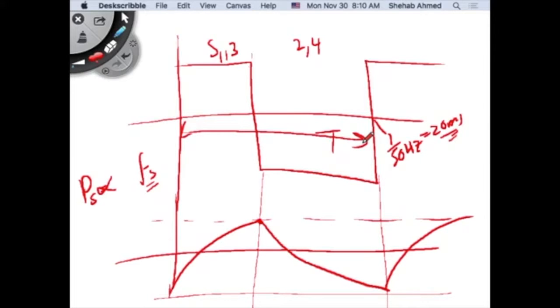The idea of switching at fundamental frequency, once every fundamental period, is a nice thing. So there's a family of converters that was developed to make use of that. And then there was a family of converters developed to try to not make use of that and switch multiple times to increase the switching frequency. So there are two main families of inverters that we will discuss.